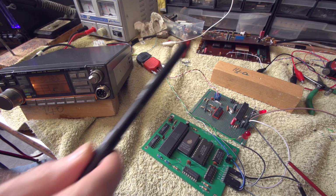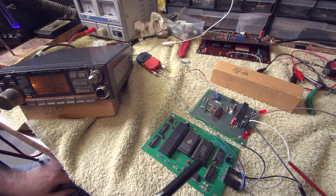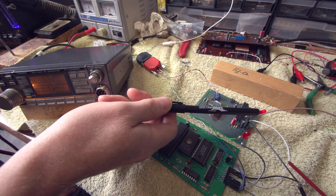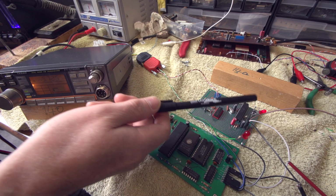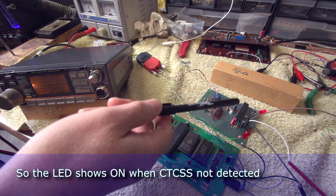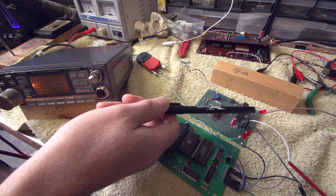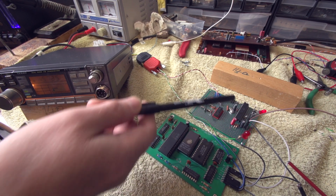Now you'll notice I've actually got the board wired up to our original repeater card, so that's come back out of the cupboard, and we've got this wired up with a couple of LEDs. This LED here is just showing the output of the decoder. It's actually active low to drive the card, so I've had to change the software a little bit to make it drive the card with a low signal rather than a high signal. Basically what's happening is the LED is in a normally on state. That means it's not decoding, everything's back to front.